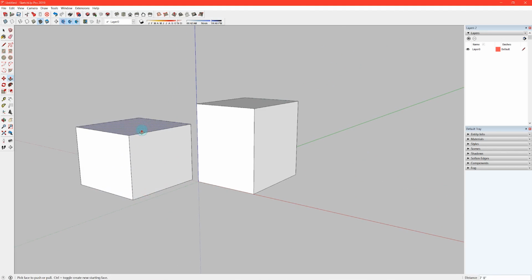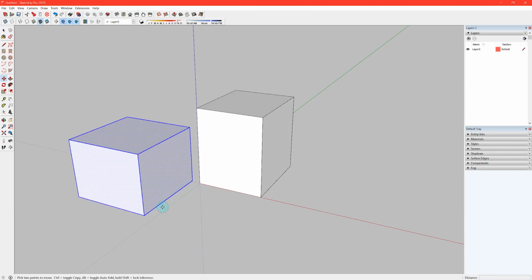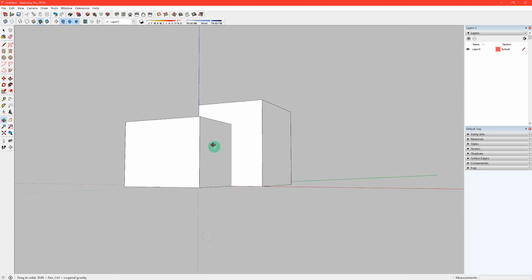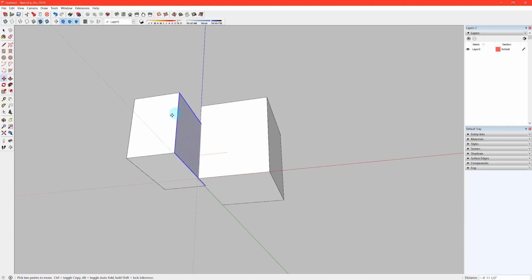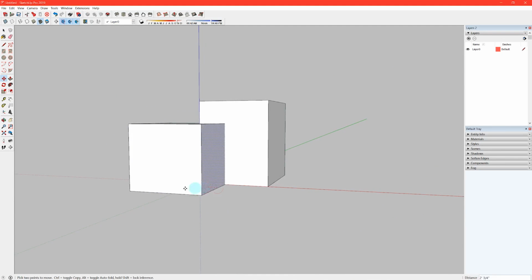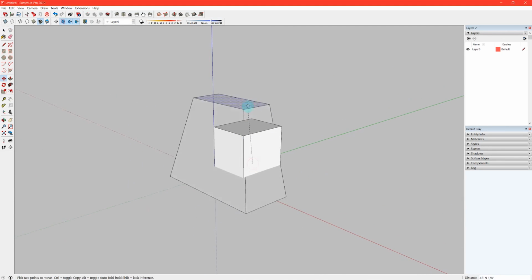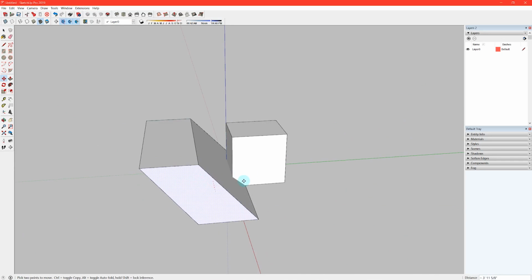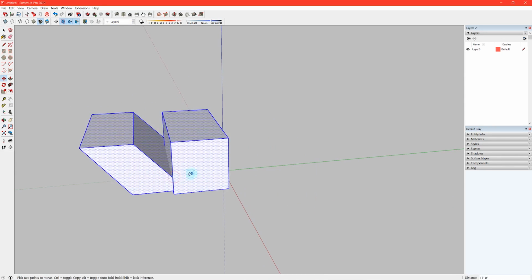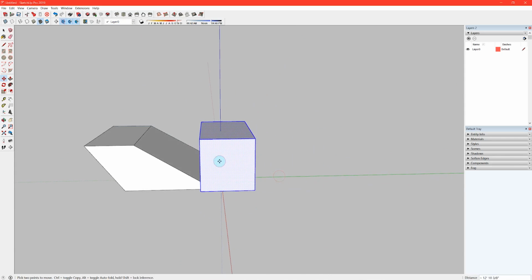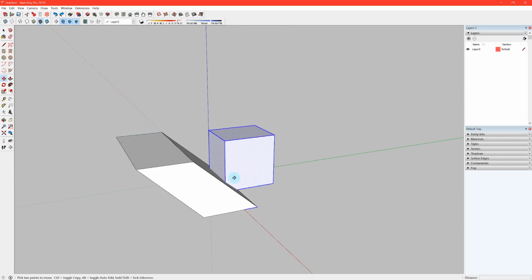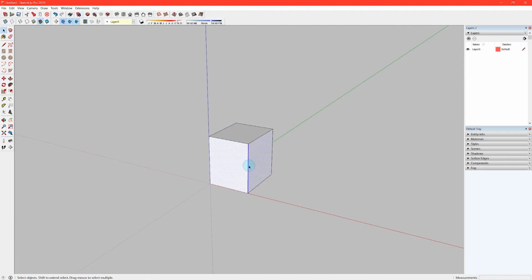So now I want to touch briefly on the modeling properties inside SketchUp. And this is pretty much the most important rule if you're using SketchUp, and that's to group or component every single thing that you model. And this is because you can see here I'm playing around with these two shapes, and whenever you draw something in SketchUp without grouping it, it sticks to everything else that's in the model. So you should never have a SketchUp model that has open groups or objects that aren't grouped. Everything should have its own group or component set to it.